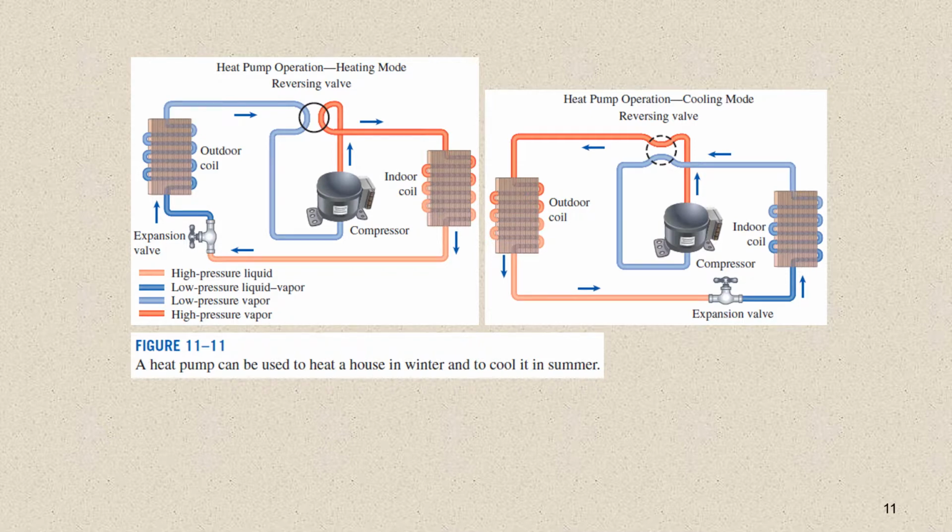Heat pumps are most competitive in areas that have a large cooling load during the cooling season and a relatively small heating load during the heating season, such as in the southern parts of the United States. In these areas, the heat pump can meet the entire cooling and heating needs of residential or commercial buildings. The heat pump is least competitive in areas where the heating load is very large and the cooling load is small, such as the northern parts of the US.